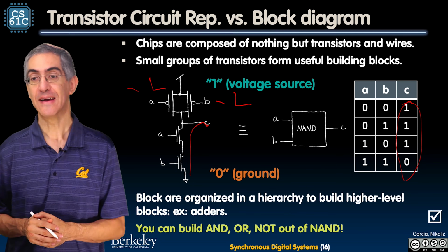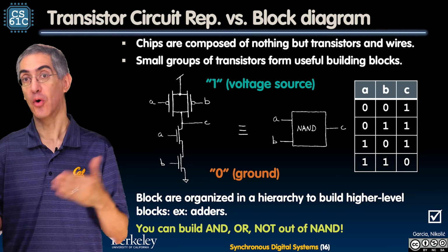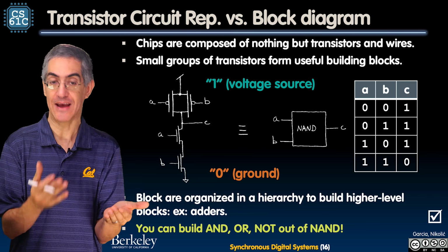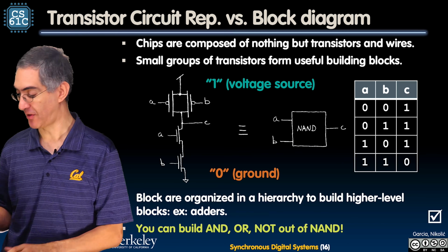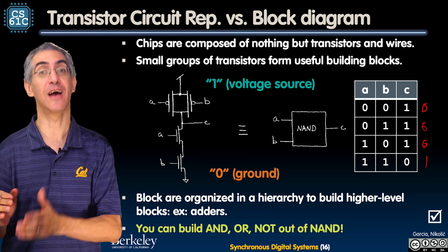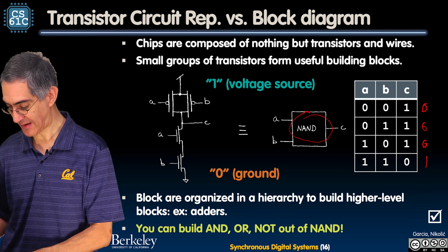We're going to see later, this is called a NAND gate. An AND gate's output is only 1 if both A and B, the inputs, are both high. NAND is exactly the opposite. So an AND gate would have been 0, 0, 0, 1. A NAND gate is the opposite of that. So this is why this is a NAND gate. And here is a NAND gate there.